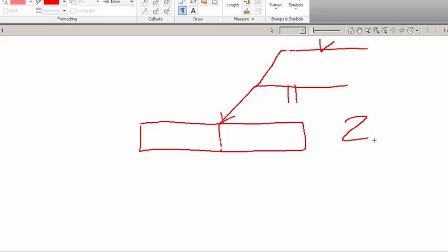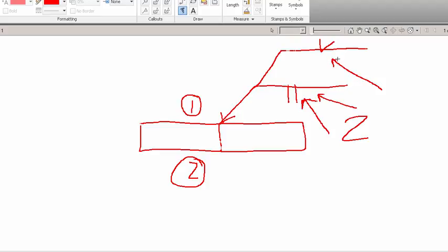which implies that we're going to do two different processes at the same connection point. Now, question number one, is this one going to be on the arrow side or the opposite side? And here's your options. This is the 1 and 2. Which one is this operation technically meaning it's going to occur, side 1 or side 2? Well, the answer is side 1, because it's below the reference line, and therefore it is on the arrow side. Note this one, however, is above the reference line, which means on the other side, so its process is going to occur on this location.